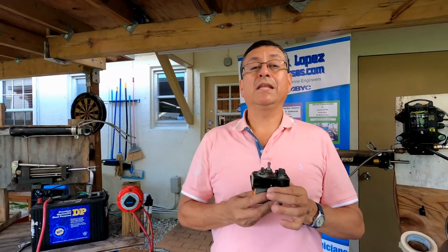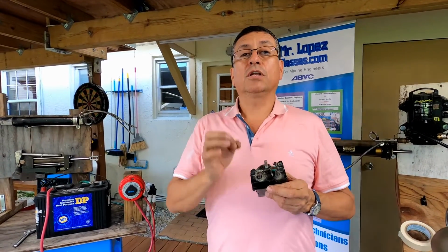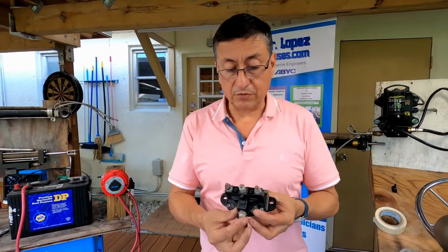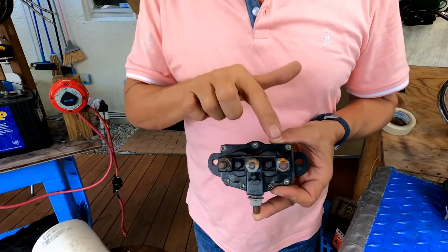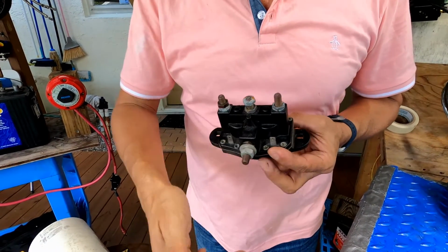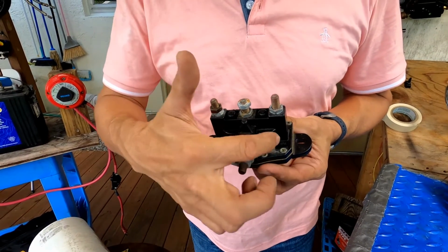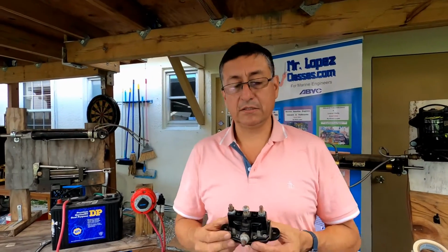Right now I am going to explain the procedure to connect the positive wire properly in order to avoid exploding the solenoid control box. This is another model of solenoid control box. Input of the positive for one direction, positive for the other direction. This is the negative, and those are the cables for the signal, right side or left side, or up and down if the motor is used in a windlass.